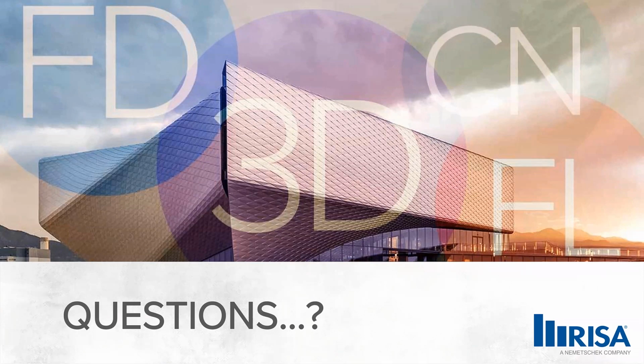So let's see, a few that were here, not necessarily in the new features, but there's a question about, can RISA Connection do a base plate with two braces coming into the base plate? Unfortunately not. Currently it's just with a single base plate in either the weak or the strong axis. It can account for additional loading in that other axis, but you cannot include that as a node and give you those additional connections.